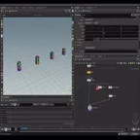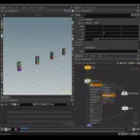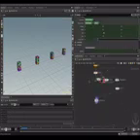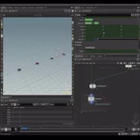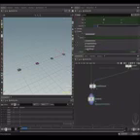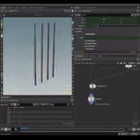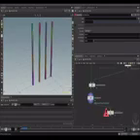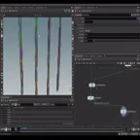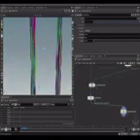Let's do it by grabbing this transform node, actions, and create a reference copy. And I'm going to plug this at the output of the Voronoi fracture. And I'm going to set the invert transformations. Here we go. Now if I explode view this, I can see our pattern is being applied.